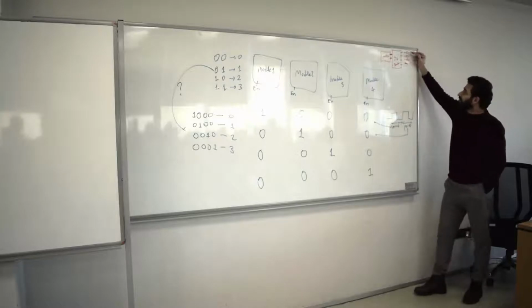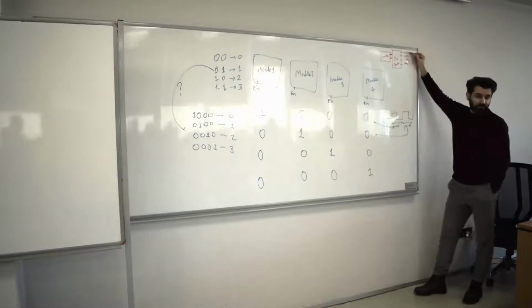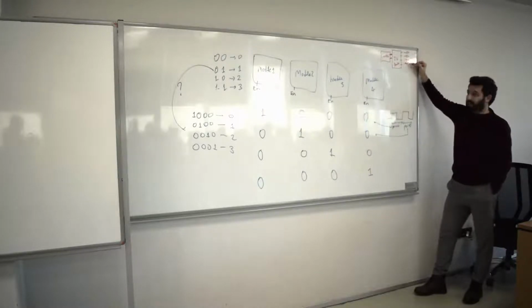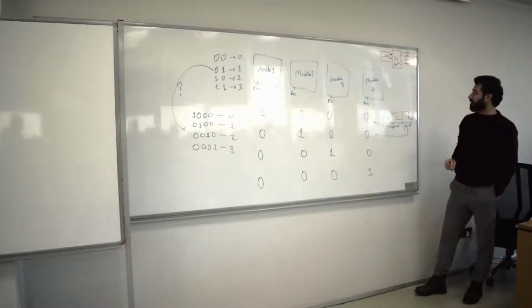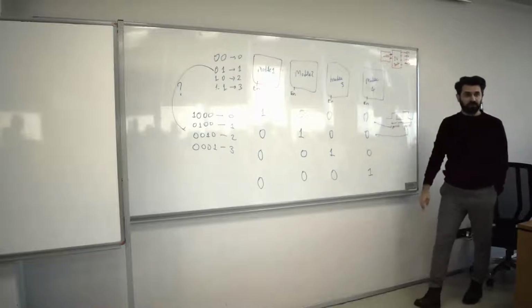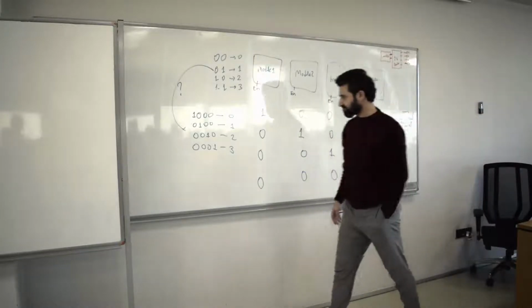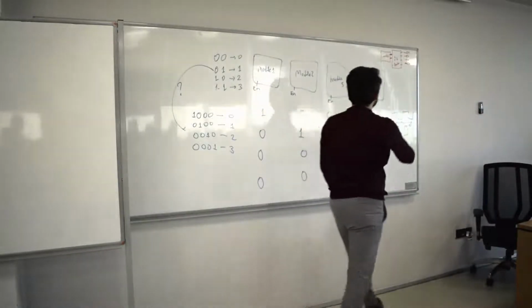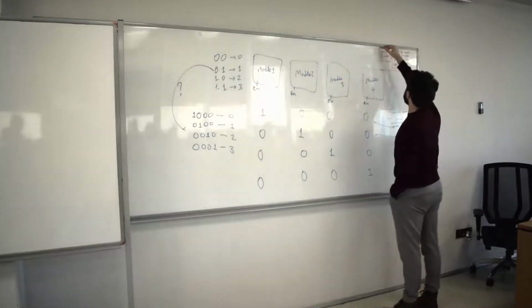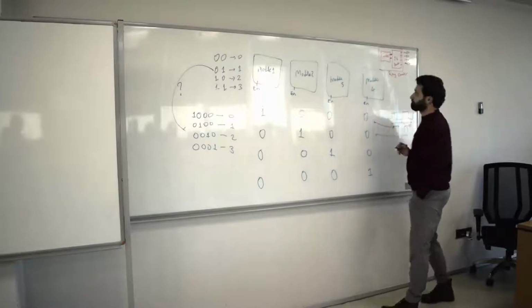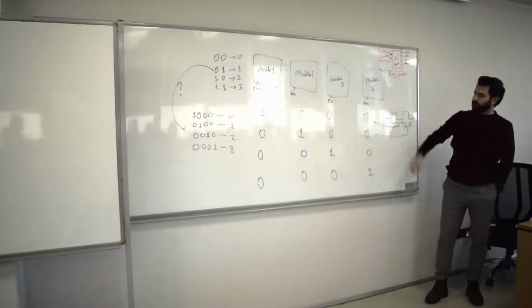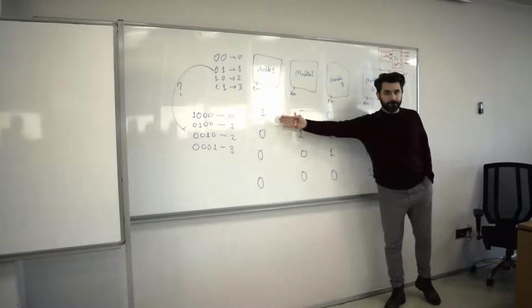It's going to be lit, for example, this one in the first clock cycle, and then this is going to be lit, this is going to turn off now, and then this is going to be lit, and then this is going to be lit, and then go back to the first one again. So it's going to circle around, and those LEDs will light up. So these 2 together are considered to be the ring counter. And a ring counter uses 4 bits, right?